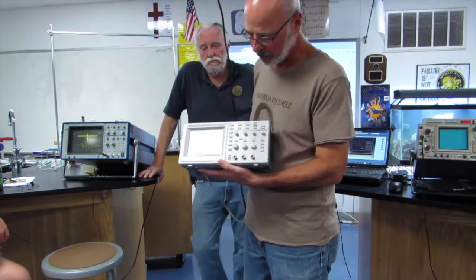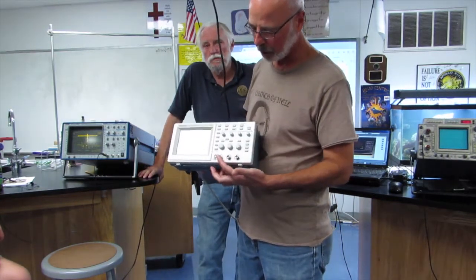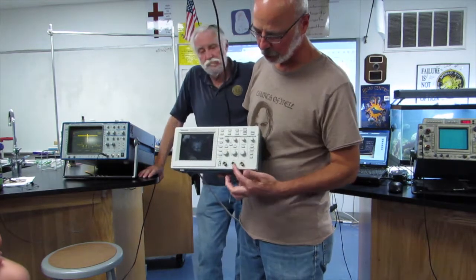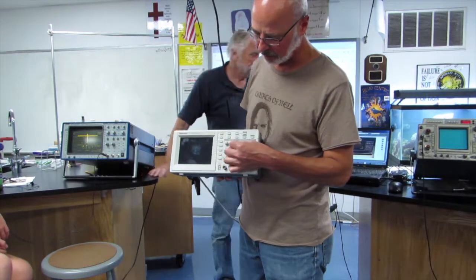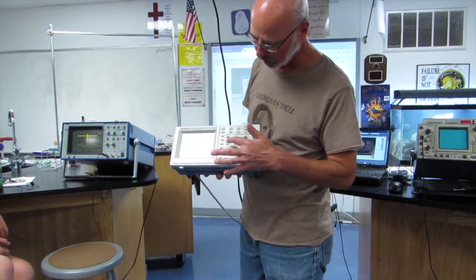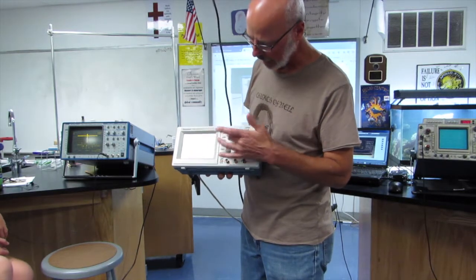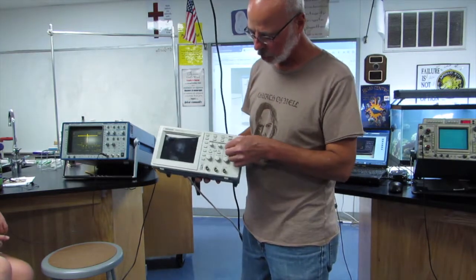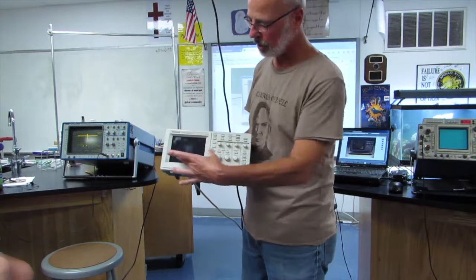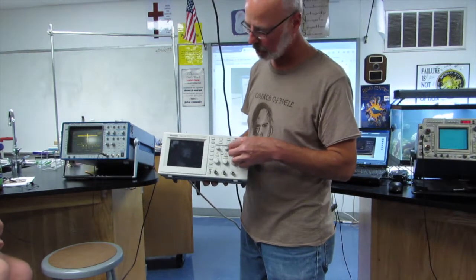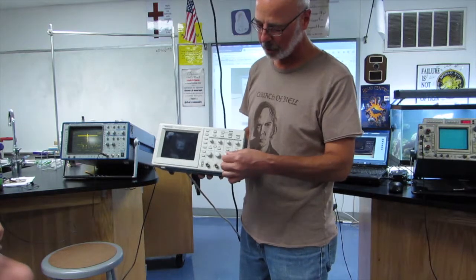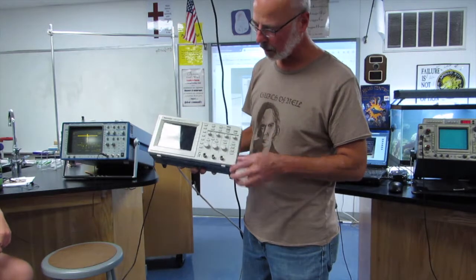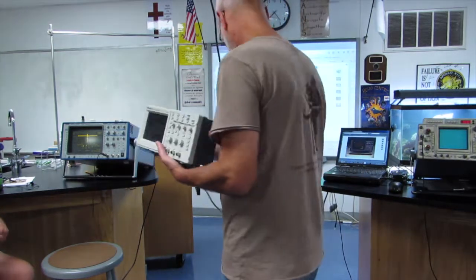Again, you've got your display and your two input channels. Here's your volts per division and your vertical position, then channel 2 volts per division and vertical position. Again, you've got your modes: channel 1, channel 2, and using other buttons you can add the two channels together. That's pretty common in scopes. Then you've got your horizontal position, which just centers your whole screen, so you don't mess with this. You just set it and it stays there. Then you've got your time per division, and your trigger level. You've got your coupling and so on. I didn't cover coupling. I don't have time for that.